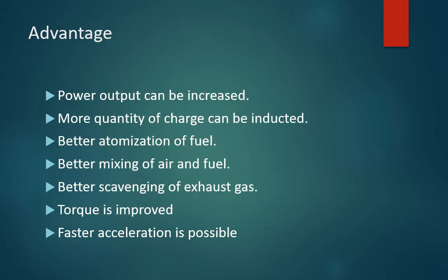When the density of the air increases, it implies that the mass of air taken into the cylinder increases. This implies that the volumetric efficiency increases, which is beneficial for us. If the volumetric efficiency of the engine increases, the mean effective pressure increases, which implies that power output will obviously increase. Therefore the thermal efficiency would become better. The better thermal efficiency of the engine is another added advantage of supercharging.